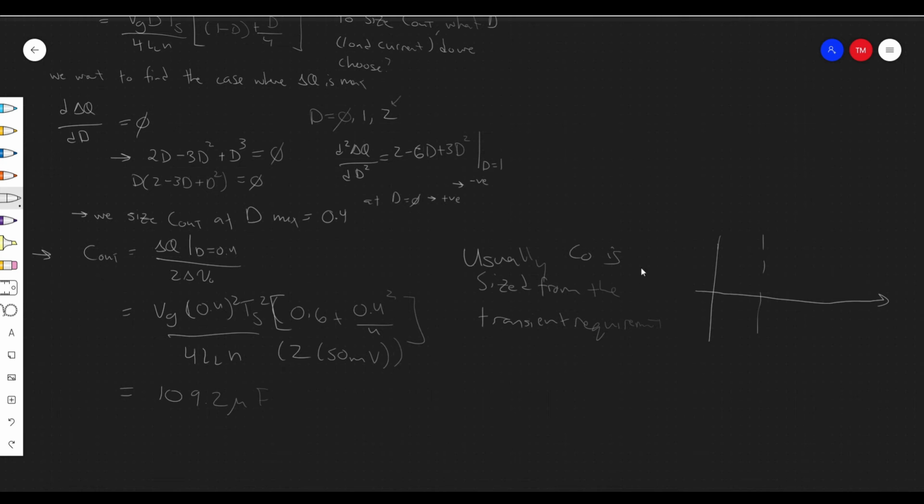So what happens in that case, you can imagine that we have some V out, right? And it's living its life, and then suddenly the output current jumps from one value to another, suddenly, right? The load demands some amount of current. The converter isn't actually able to respond instantaneously to these very sudden changes. So the output voltage for a short period of time, the current that you're providing doesn't match the load current, so the output voltage drops a little bit and then recovers to the value